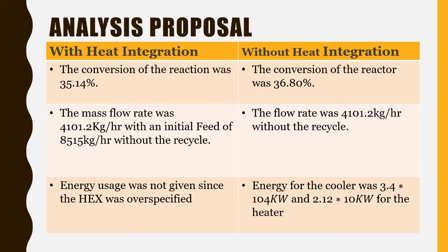The last one is the energy. Energy usage was not given since the heat exchanger was overspecified, and if it was not overspecified, it was underspecified, and if it was not underspecified, it had temperature cross and FT correction factor was missing. This is the problem for the one with heat integration in our simulation.